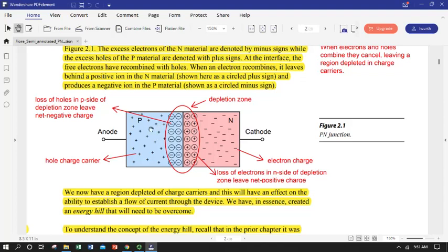And likewise, we expected the p-type material to have an excess of holes, and now we took those away. So a neutral state seems negative from the viewpoint of a p-type material that wanted to be positive, and neutral intrinsic semiconductor material seems positive from the viewpoint of the N material that wanted to be negative because it's got a lot of excess electrons, majority charge carrier.